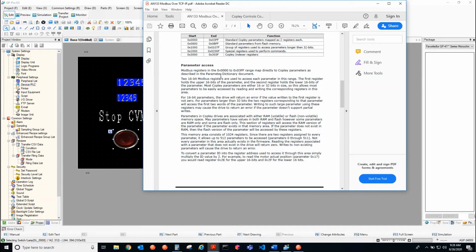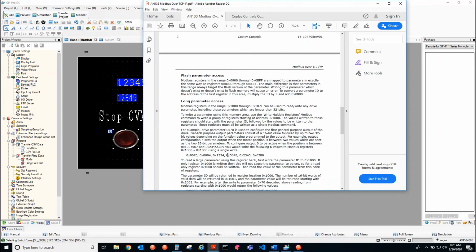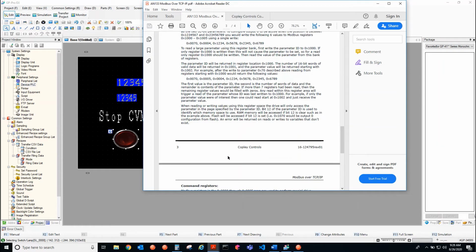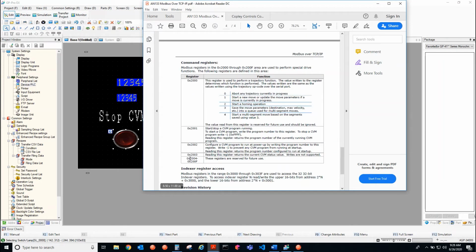Oh no, wait, we'll be sending it to 2000, the special register to perform commands. If we go down, okay, here it is. We'll be writing to this one, 0x2001, start and stop a CVM program.